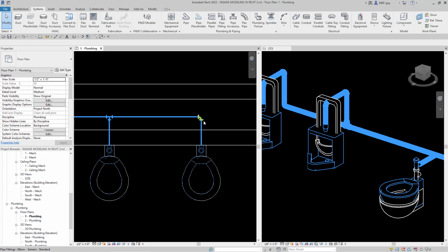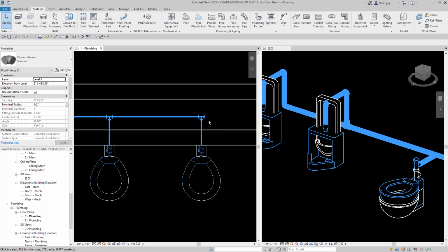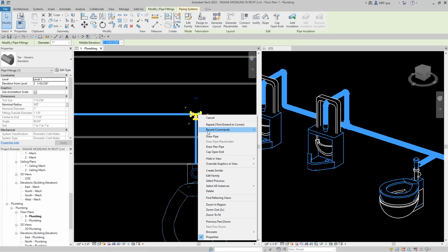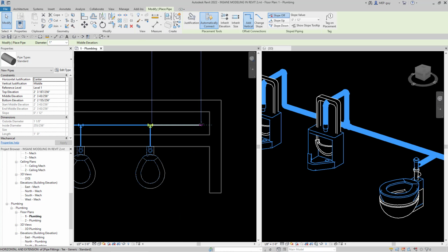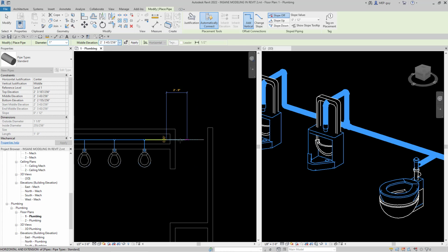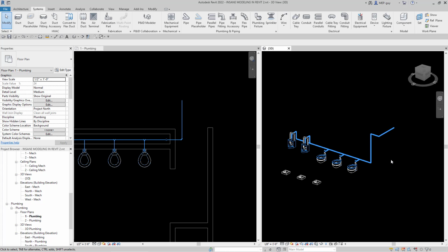Now we'll click this little elbow fitting, and we'll make sure we hit the plus right there. Click on the fitting, right click, and we'll draw some pipe. And I'm going to draw it to about this position right here. And now we'll bring it up to about 9 feet. And we'll go from this point right here, and this is where our main piping is going to be originating from over here. So let's go ahead and size this system real quick.